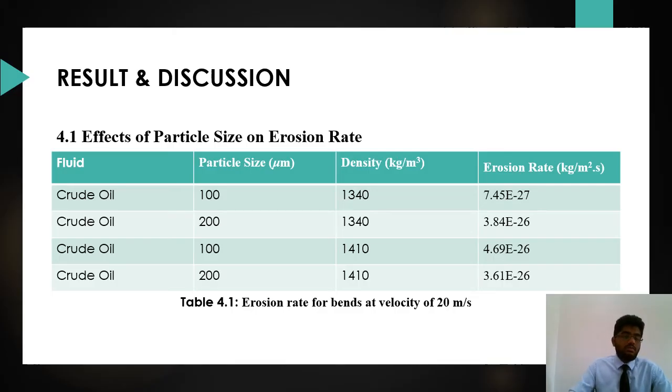First of all, I would like to explain the effects of particle size on erosion rate. It is significant to study the effects of particle diameter on fluid-solid interaction, as particle size in different systems varies to a large extent from nanometer to centimeter. The particle diameter has direct influence on drag force and therefore affects the flow behavior.